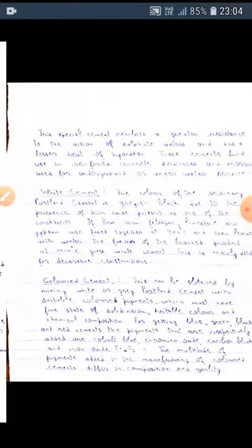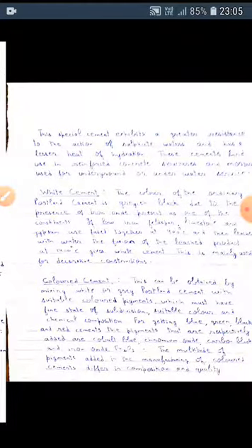The paint applied on the surface of structures in which colored cements are used must not fade, and architectural finish must retain its coloring, offering proper resistance to weathering. The color of the aggregates intended for colored cement, mortars, and concretes must suit the cement binder. Colored cements are tested by physico-mechanical properties. Colored cements are packed in multi-layer paper bags.